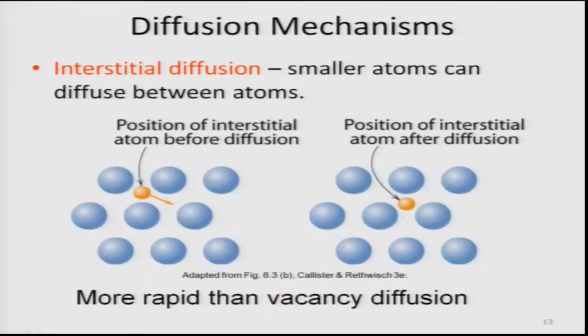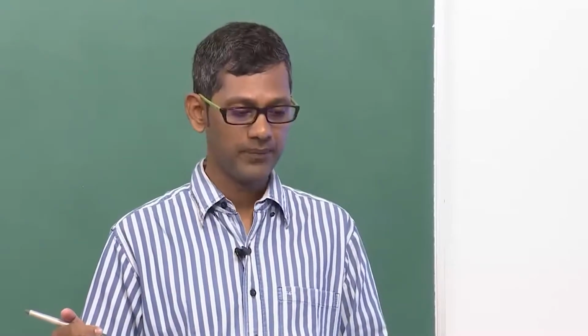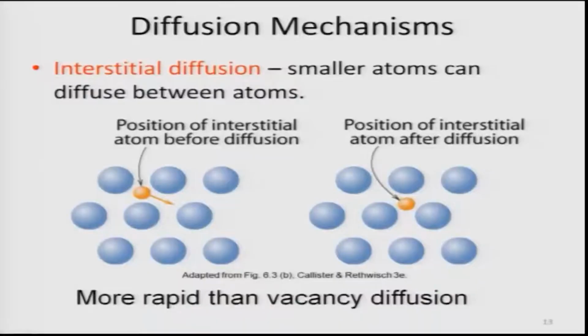Okay, many situations are possible. But a similar situation is not true when you have interstitial atoms like carbon in steel, or boron in a nickel aluminum alloy. Atomic size is very small, so they will be sitting in interstitial positions. Interstitial position means that in between these lattice positions there will be interstitial positions like octahedral voids and tetrahedral voids. I already told you, again taken from Callister.